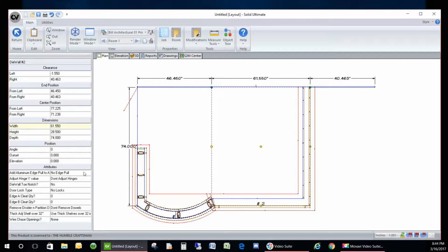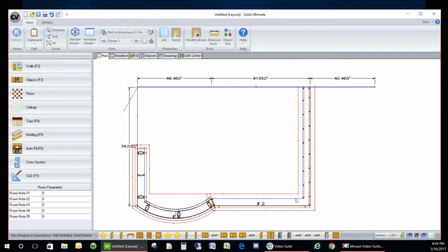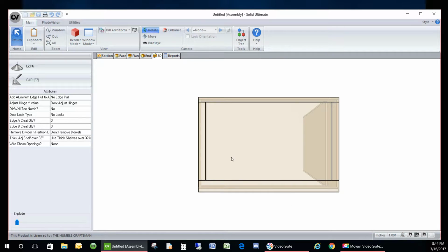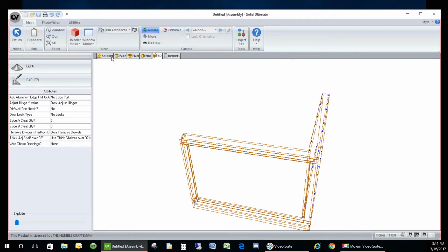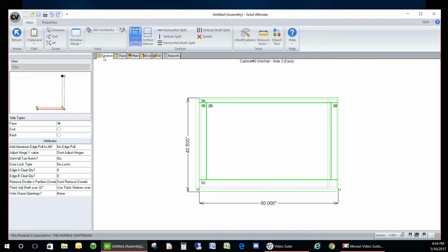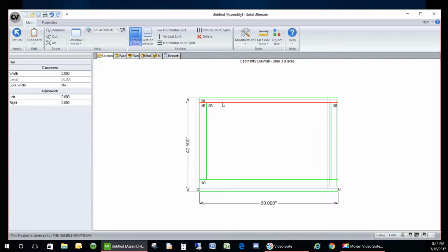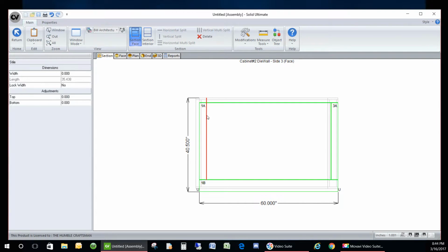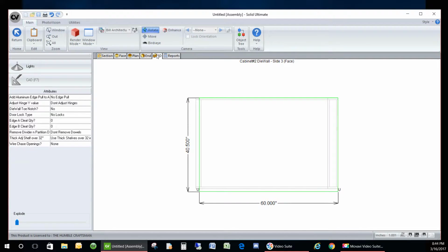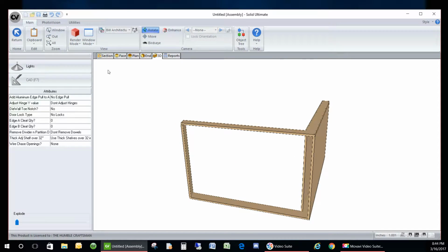Now, before we start editing sides, we're going to go ahead and change the height on this to 40.5, because this is our higher wall. So now we'll double click on this, and by default there was already some sectioning done in the library, so we'll just go ahead and delete all of these cabinet sections so that we can just have that.